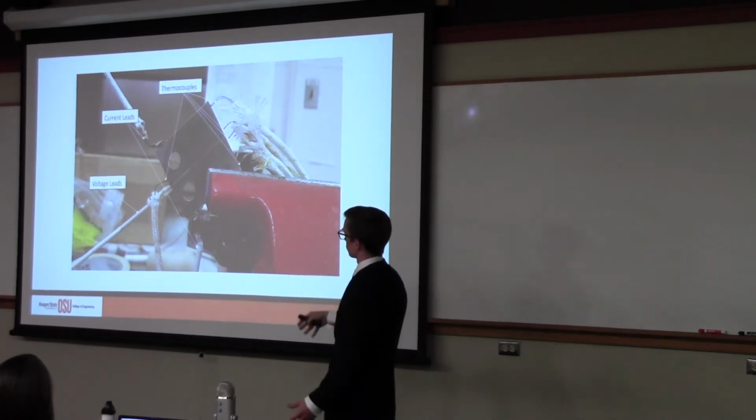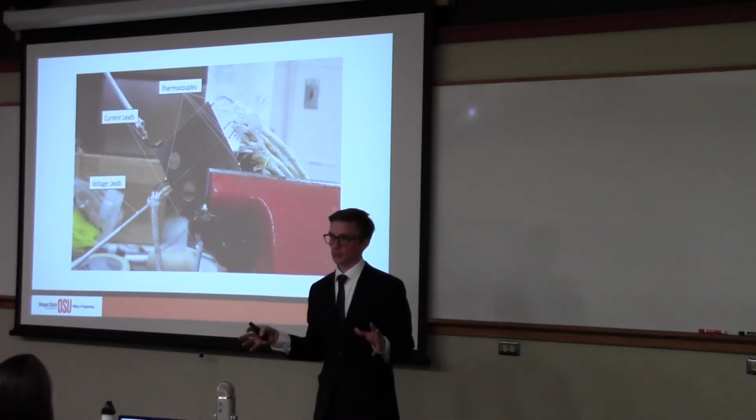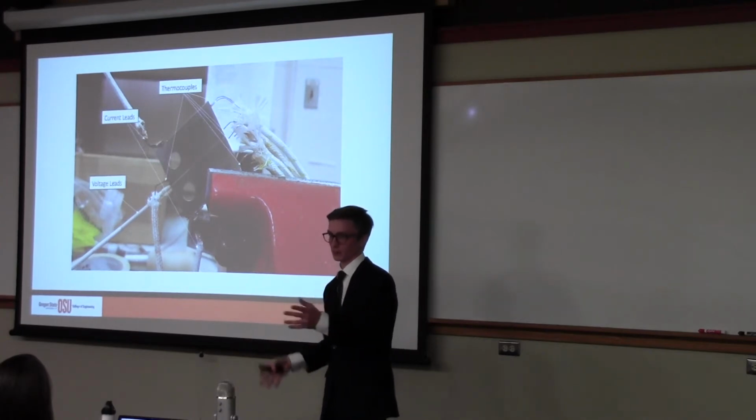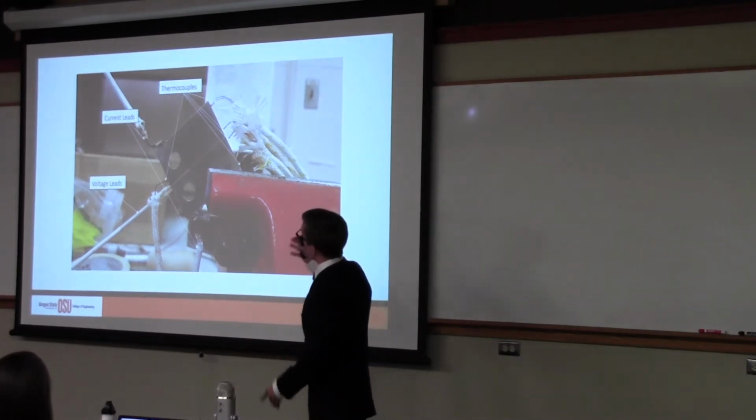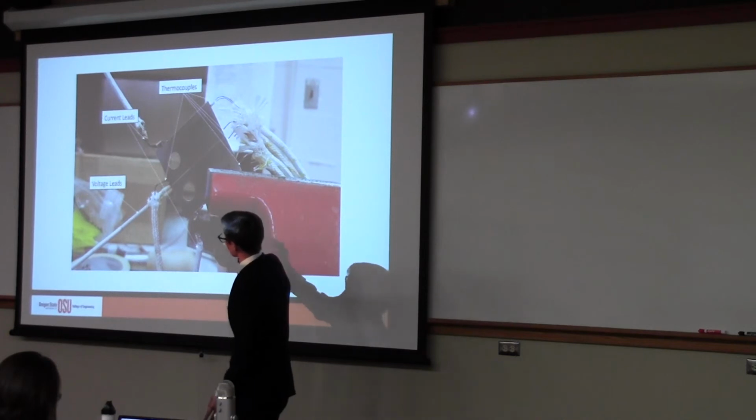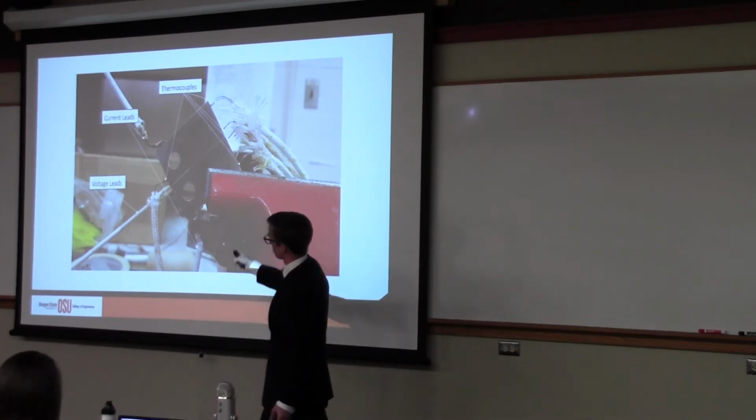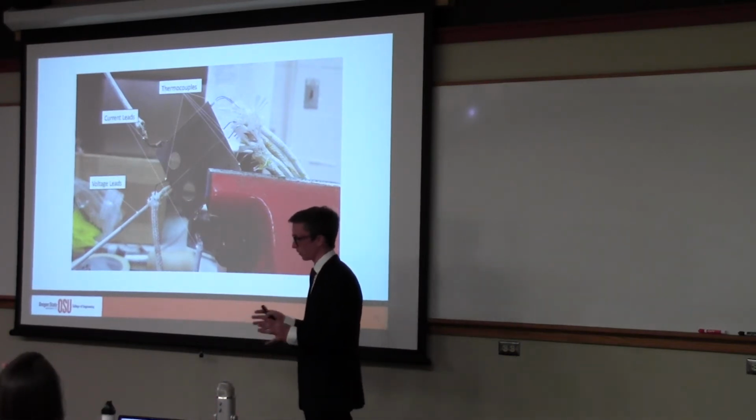I've spot welded 5 thermocouples on it, mostly redundant because at least a couple of them are going to fall off by the time you get in the machine, the shell knows. So those are thermocouples. Then we have our electropotential drop system for measuring crack growth, and the whole point there